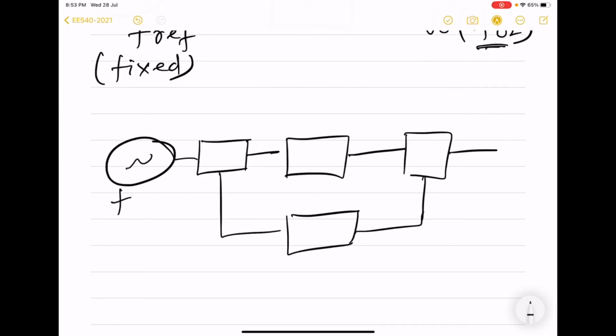So here we have our external reference signal, and here we will be getting our output. And we will be able to change this output frequency with the help of block, which is called divide by n block. And this output will be actually produced by, again, an oscillator.